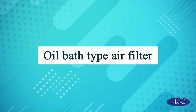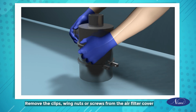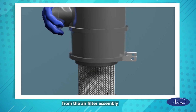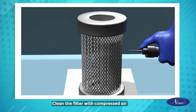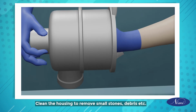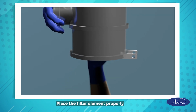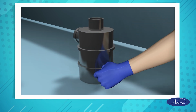Oil bath type air filter. Remove the clips, wing nuts or screws from the air filter cover. Remove the cover. Take out the wire mesh filter element from the air filter assembly. Drain the oil in the filter housing. Clean the filter with compressed air and clean with a soft cloth. Clean the housing to remove small stones, debris, etc. Fill the oil up to the mark mentioned in the filter housing. Place the filter element properly. Fix the cover and lock with clips, wing nuts or screws.